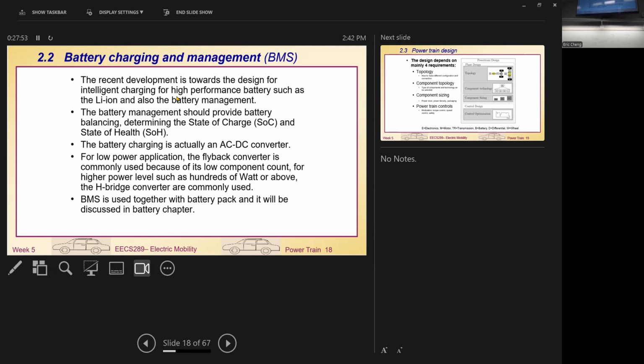However, the battery does age. Usually it lasts around 7 years, and some of the good ones maybe 8 years. Most manufacturers only guarantee 4 years. So that means we need the BMS in the battery system to make sure the battery is working well, including all the protection, and SOC and SOH management.